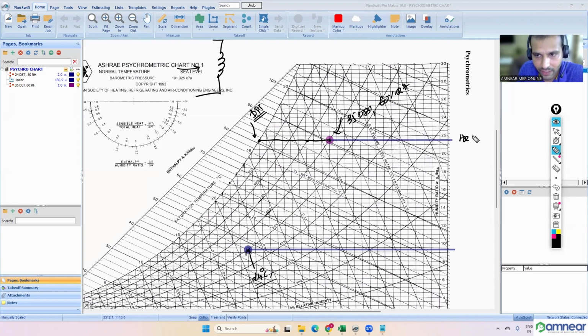So for 35 degrees Celsius dry bulb temperature and 60% relative humidity, just understand, the humidity ratio is 21.5 gram only. Now this is 35, 34, 33, 32, approximately 32 point something. Let's say 32 degrees Celsius and 70% relative humidity. What is the humidity ratio? The humidity ratio is the same only. So the humidity ratio remains the same for various states. Even if the dry bulb temperature and relative humidity are different, it may have the same humidity ratio.